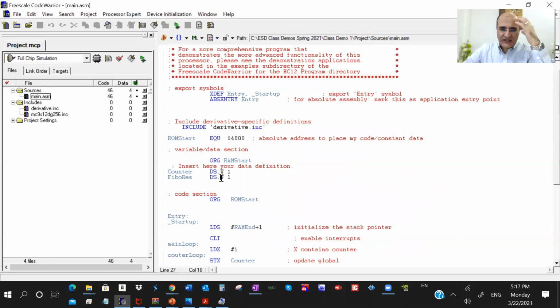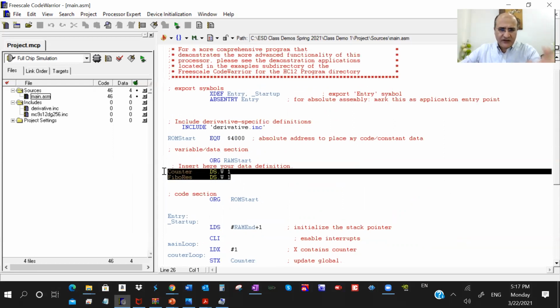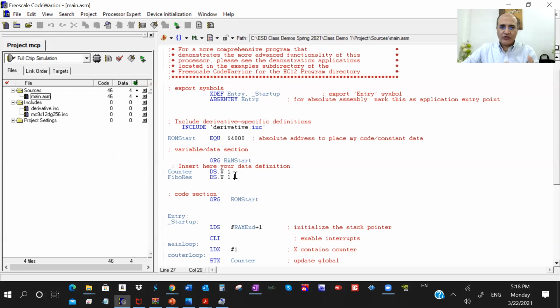These are for the assembler, when you go build your assembly program and create the executable. These are not instructions, they are directives, commands given to this assembler running on my laptop, how to behave when it builds the program. But the result is not included in the executable that's going to run on the microcontroller.